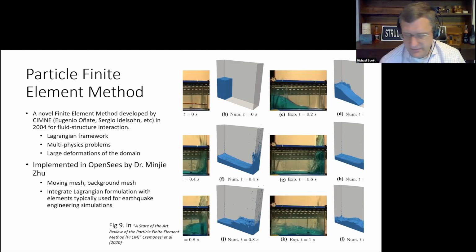So the coupling of fluid and structure is almost natural and doesn't rely on a staggered kind of approach: solve the fluid, solve the structure, in two separate systems, and then go back and forth. It's all monolithic, as we say. Very good for multi-physics problems like FSI, and also can account for large deformation.